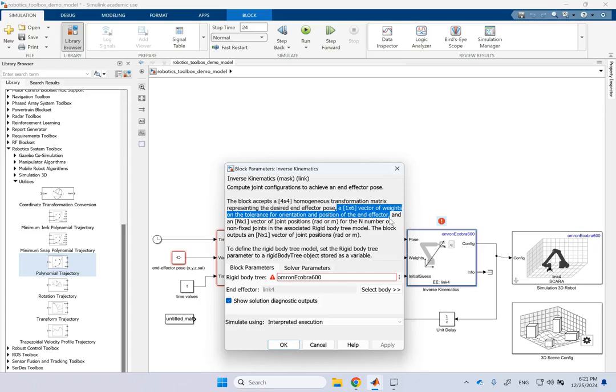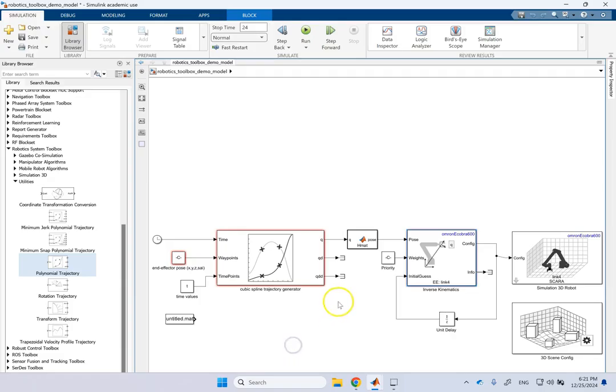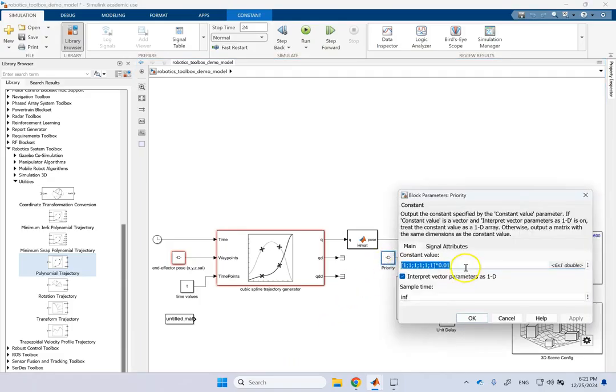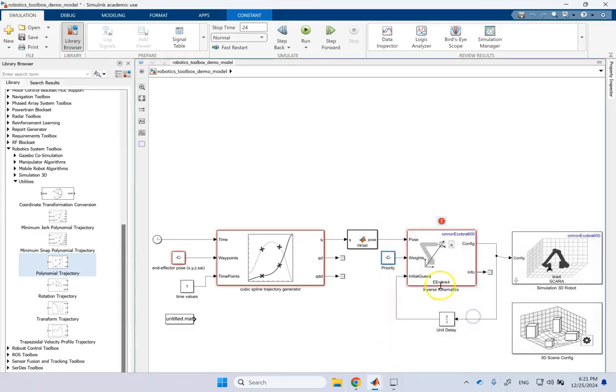Okay, for a writing purpose, you might not care too much about the angle of the end effector. What you care about is x, y, z, because you're writing on a flat piece of paper. Now here I have given them all the same weight, but as I said, you can use tighter tolerances on these first 3 and lighter tolerances on these last 3. Okay, so this is the weight.